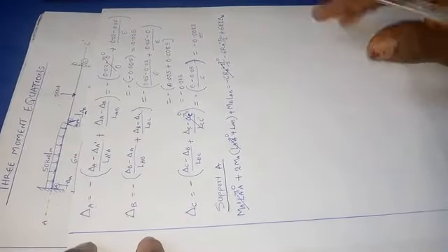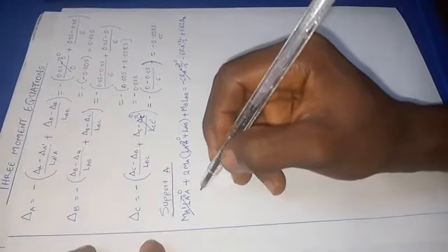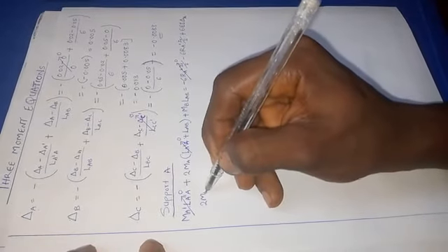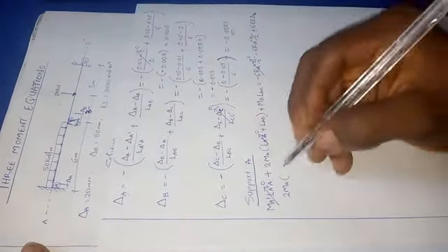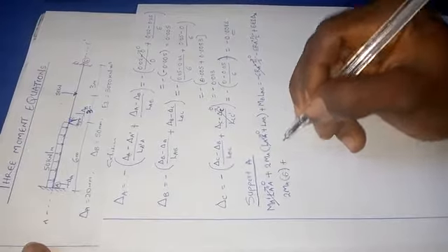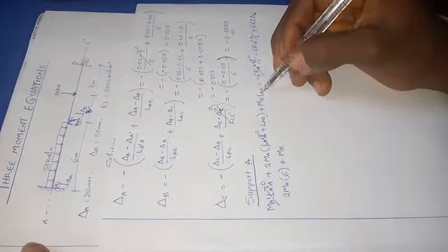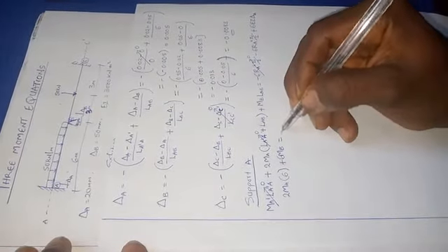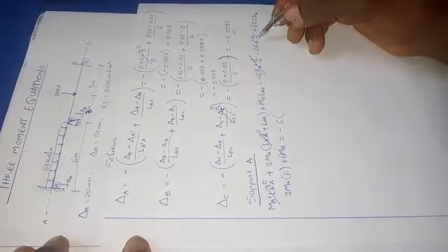For the remaining part of the equation, I'll have to be substituting. The next thing I have to do here is 2 moments at A multiplied by the length of A to B. The length of A to B was 6. Then plus, I don't know the moment at B, so I included moment at B multiplied by the length of A to B, which was still 6, which is equal to minus 6 in bracket the reaction at A right.